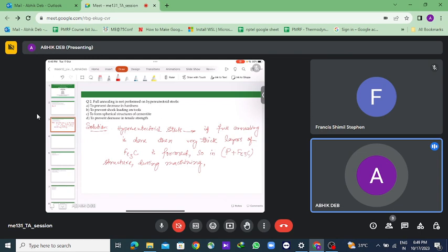the effect of strain hardening or refining grain structure. So there are different kinds of annealing. One is full annealing, that is complete annealing that we discussed now. Then there is spheroidizing, in which spherical structures of Fe3C are formed in a pearlite matrix. Then there is process annealing, and then there is stress relieving. Okay, so in stress relieving, the material is heated just below the lower critical temperature, so that there is softening and the residual stresses are released.